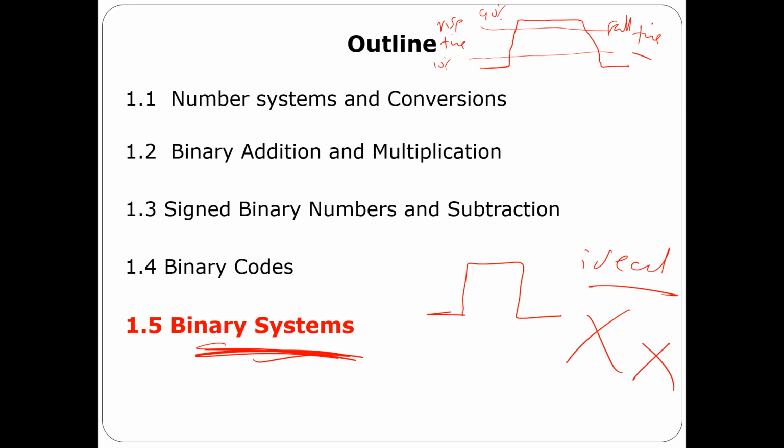The other thing I want to explain is, okay, if I have an inverter this way and I put 0 here, do you think I'm going to get 1 at the same time? The answer is no, there is a delay. We call it propagation delay. So what happens is that if I give this input this way, the output is going to be shifted for some time because there is a delay. This is something normal, there is a delay, okay? And this is something I want you also to measure in the coming lab.